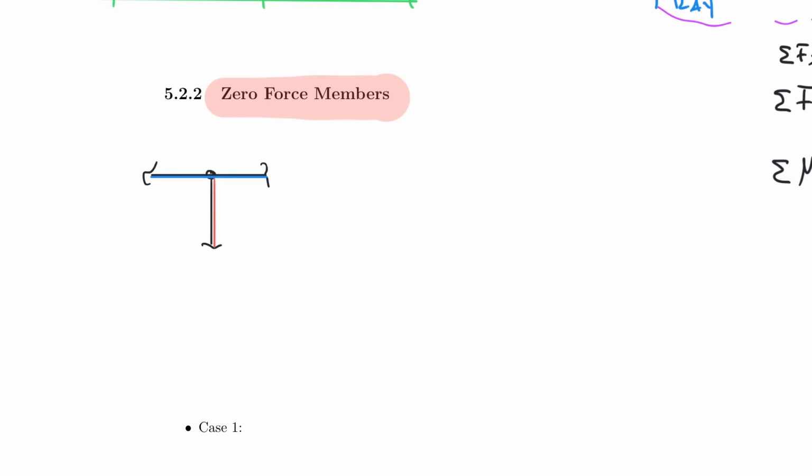This one here actually happens to be not random. It's perpendicular. But remember that for this case, it's easier to see that any force acting perpendicular to this system cannot be resisted at this node, because you cannot create equilibrium here. So let's say you pull on this member, it's not resisted up here. Therefore you only have one force in one direction, and you cannot create equilibrium. That means that this member here must be equal to 0.